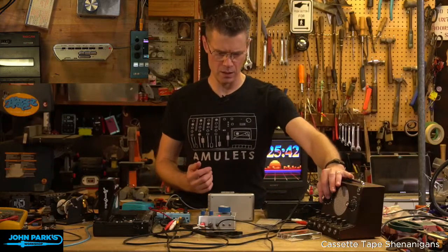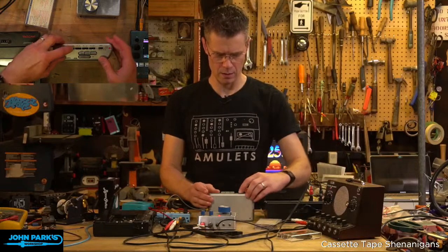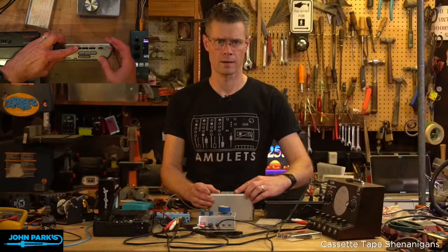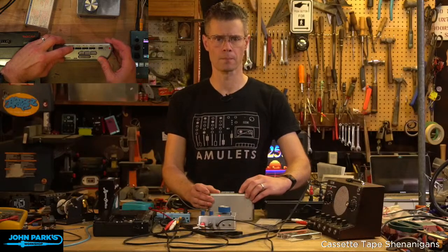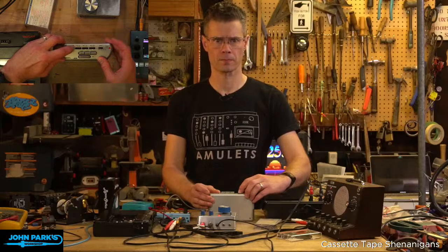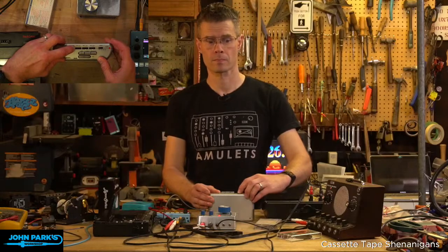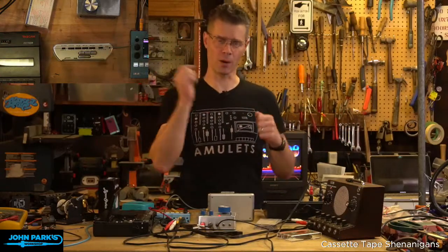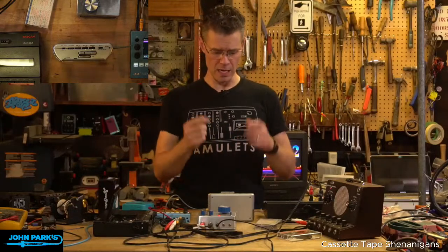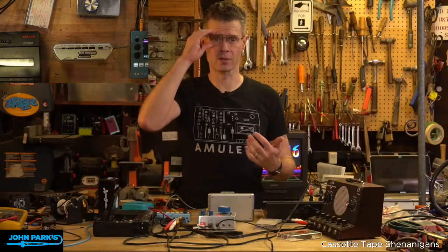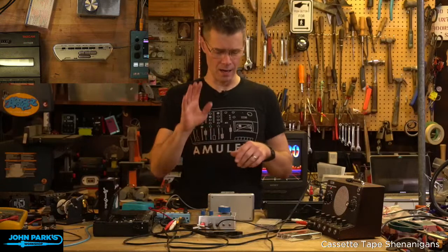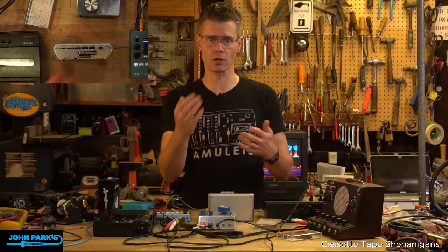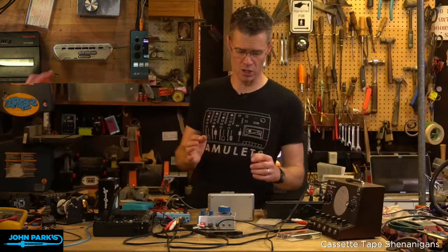Okay, so this is a little droning synth thing I recorded. You can see here, this is just using this pitch control. And you can see there, we're sliding between those pitches. If instead we could jump there, I was just trying to jump really quickly between some settings, you could play it sort of like a Mellotron, which is an old keyboard that had essentially a tape loop per key. So getting rid of that sliding, that would be the idea behind using something like a digital potentiometer, where you could just go directly to a different resistance level for the speed controller on the motor and get it to play back the way you want it to without all that slide.